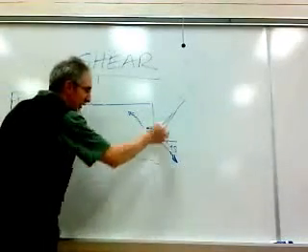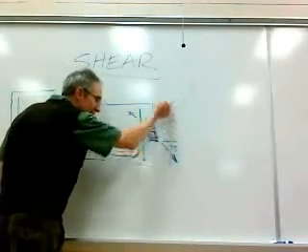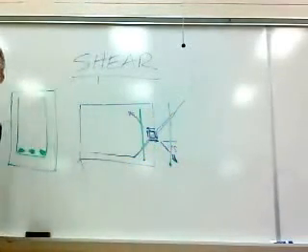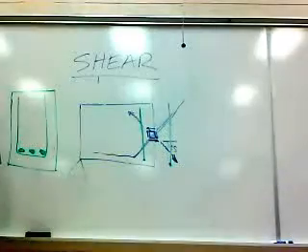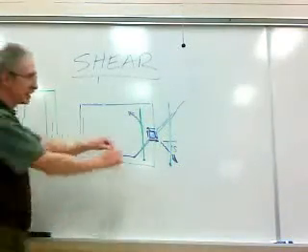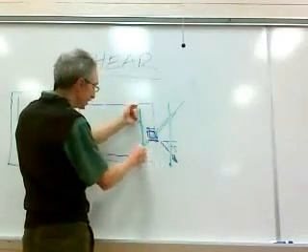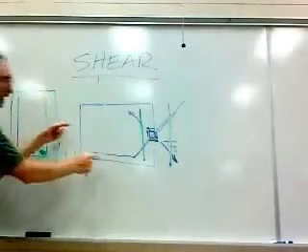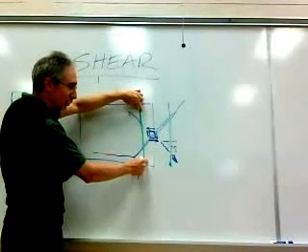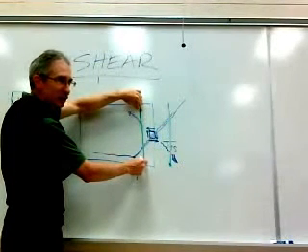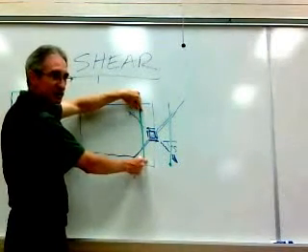Okay? Well, guess what? If I've got a stirrup here and maybe another stirrup down there, what are those stirrups going to do? They're going to try to keep the beam together. Because as this thing tries to pull diagonally and cause the crack this way, if I've got this steel anchored in the piece of the beam that's down here and the piece of the beam that's up here, what's this stirrup actually going to be placed into? Tension. And it's steel. And steel's good in tension.